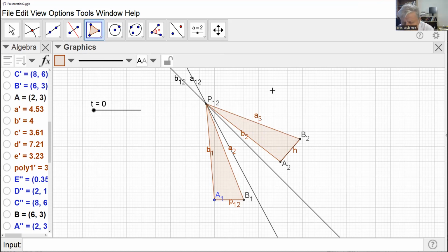Originally, we don't know the shape of the rigid body. We are going to assume that the rigid body, the moving plane, is of infinite dimensions. What we mean is determine that point P12, and attach that plane to the fixed frame by a revolute joint over there. Now, this is his theorem. You are able to rotate this rigid body from the first position to the second by a pure rotation about P12. Now, can I prove this?